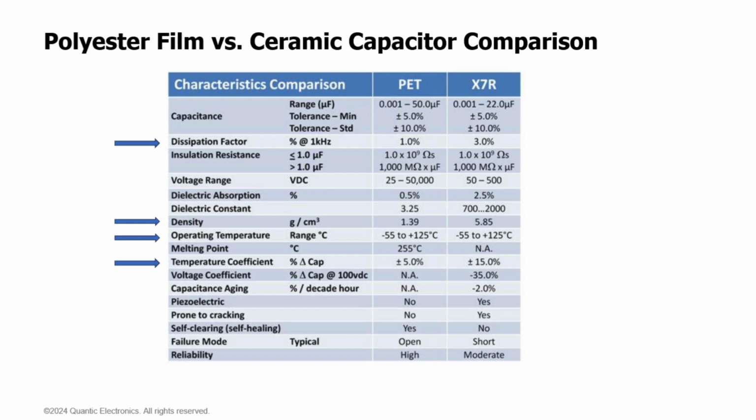The latest advancements in ceramic technology are reducing dielectric thicknesses to as low as 0.5 micron, which is significant, increasing dielectric strength to as high as 35 volts per micron. So taking those into consideration, these values are actually approaching what today's commercially available film cap technologies are able to achieve. So in many ways, ceramic is coming up onto the same level as film. So later we'll review what film is doing about that.